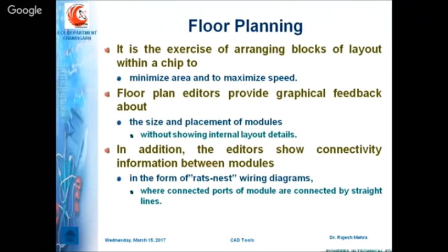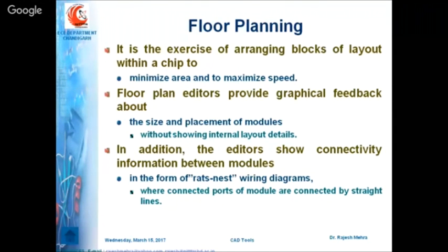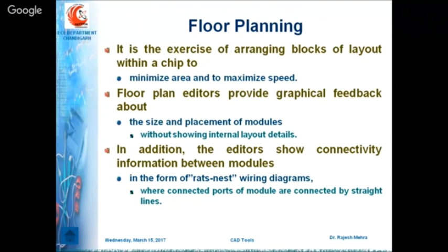Then this placement and basically routing, it is dependent upon the floor planning. If you have PLDs, you have prefabricated CLBs and PLBs in it. If you have any semi-custom ASIC design, again you have prefabricated resources on that semi-custom chip. Now you have to place your design on these prefabricated resources. So how to place your design on these prefabricated resources, that will depend upon your floor planning option. And how to select the floor planning.